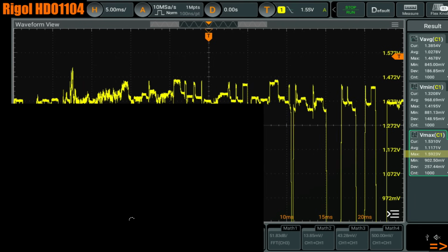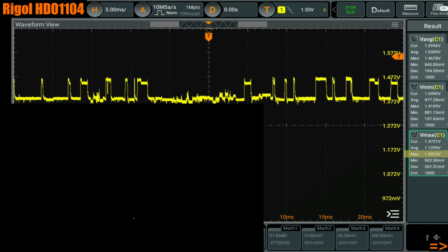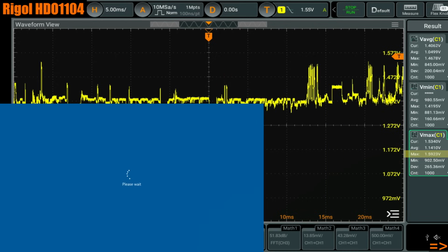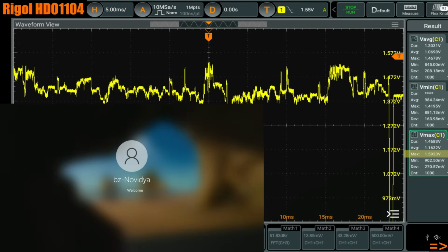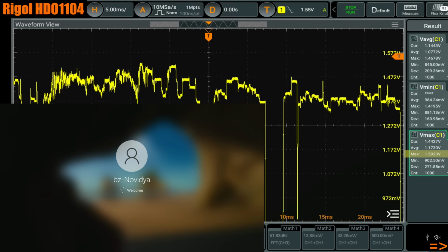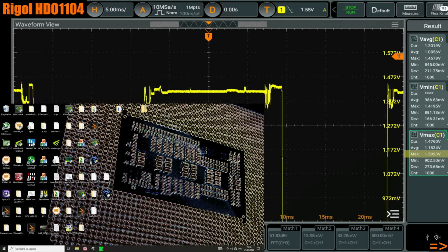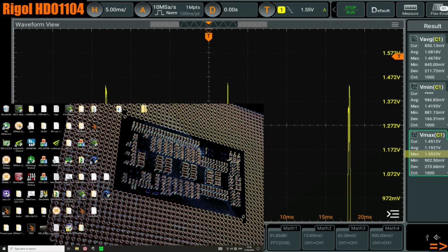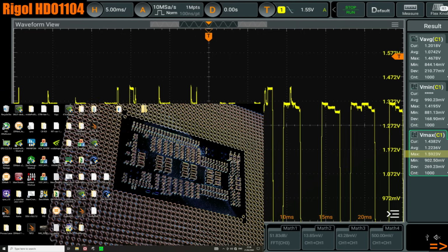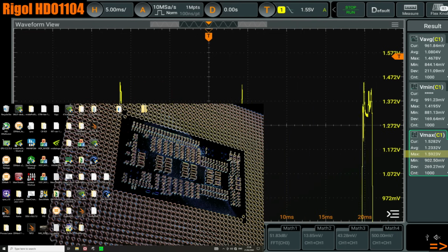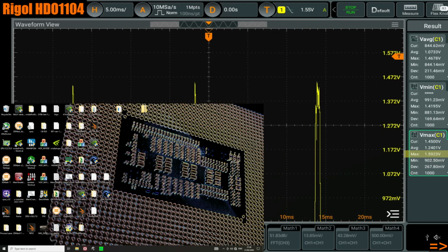And as far as I can tell, that seems to be some kind of bug with the voltage regulator. I kind of suspect it might be because the Intel default profile uses a really droopy LLC. In my past experience with some MSI motherboards, on very high vdroop LLC settings they have weird issues a lot of the time. Because I think MSI fine-tunes the voltage regulator for relatively shallow load lines, and when you slap a really deep one on it, it causes all kinds of weird issues.